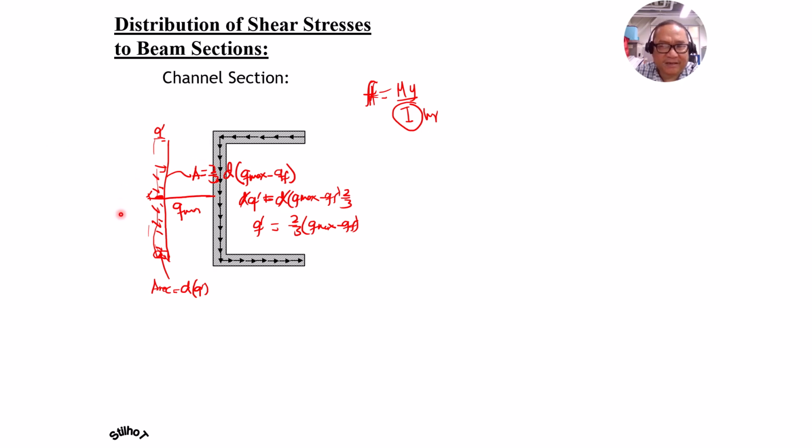So we have here the shear, this one F, and this is also F by symmetry and equal in length also. So the vertical shear is denoted by capital V, and this is F. So the shear stress distribution would be 0 here, then it's relatively maximum at this junction, triangular in section.